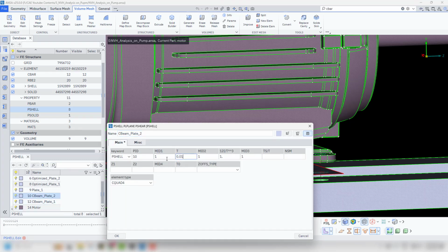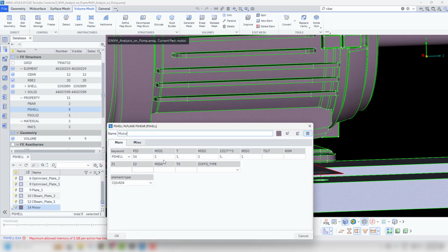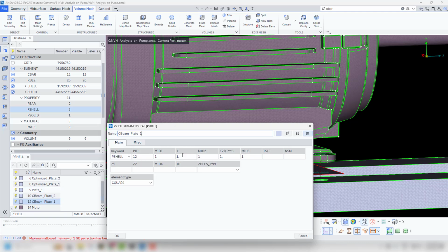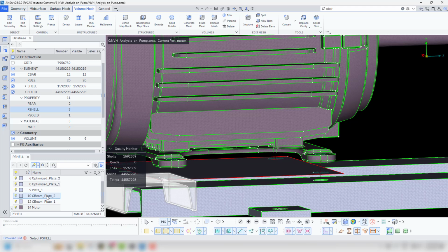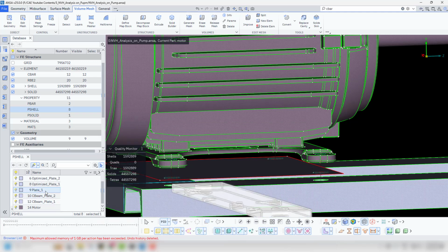And for the remaining shells, now it's solid component analysis. For that, I would like to keep all the shell components at minimal thickness, that is, membrane. If you keep the thickness less than 0.01 or 0.1, it will be treated as a membrane, so it won't impact the structural analysis or any analysis of the solid components, in short.